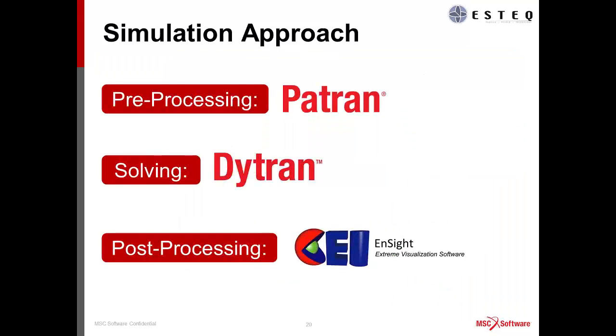Alright, so for pre-processing I typically use Patran, solving with Dytran, and then post-processing will be performed with Insight in my case. This is a really powerful tool for visualizing the results. I know there is ParaView available as well, which can do a good job. That's something that I really recommend if you are going to be performing mine blast analysis. Using a third-party post-processor really does assist things quite significantly.